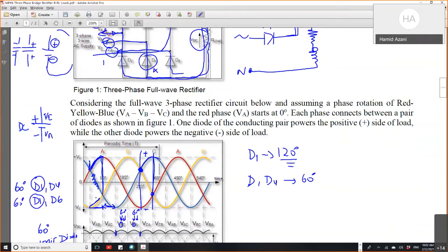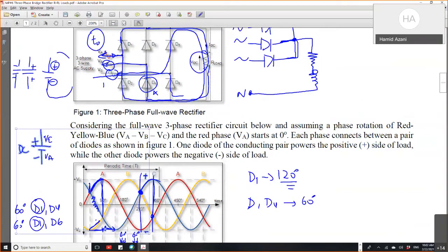That's VA. The currents go through VC, but which diode is connected to VC? Forget the bottom ones, because they have cathodes. They will block any circulation coming from any one of those phases toward the load. But the ones at the top will allow that current coming from one of those phases and going to the top side of this load.